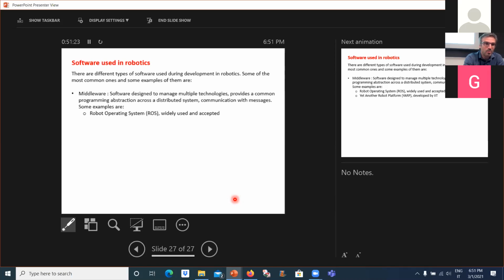which stands for Robot Operating System, and is mostly used in robotics. It is a data messaging communication technique where, for example, you write your controller in a node that communicates with messages with the sensors, provides messages, and sends messages to the actuators. The problem of ROS is that it's not real time.